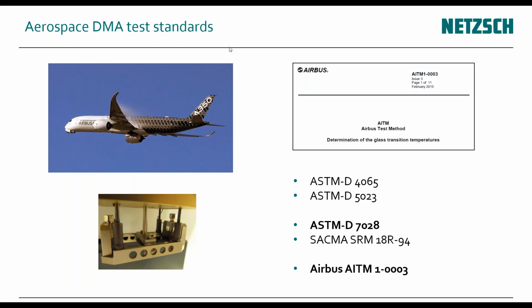So there's no necessity from a physics point of view to do this in tensile mode or shear mode, which would require a very, very high force. We only want to see this temperature transition, the glass transition, and that can be done very nicely in a bending experiment, let's say cantilever bending, as this is done here. Three-point bending would obviously display very similar results, but basically you do this in bending.